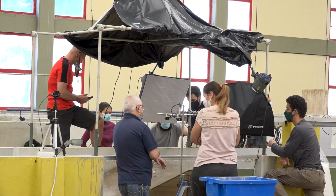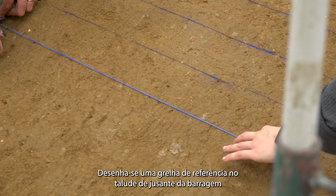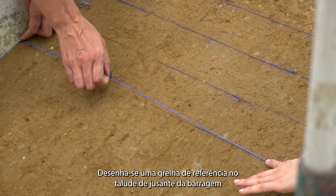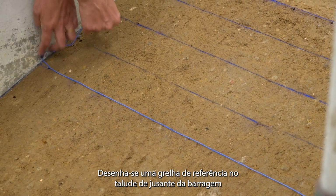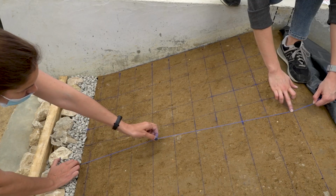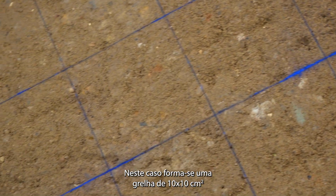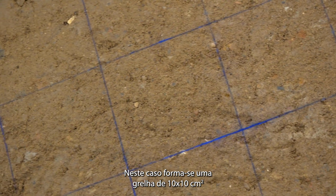Once the embankment dam is constructed and all equipment is placed, conditions are met for the failure test to take place. On the day before the test, the following steps are taken. The reference grid lines are drawn on the dam downstream slope. This is achieved with a chalk line reel. In this case, they form a 10 by 10 square centimetre grid.